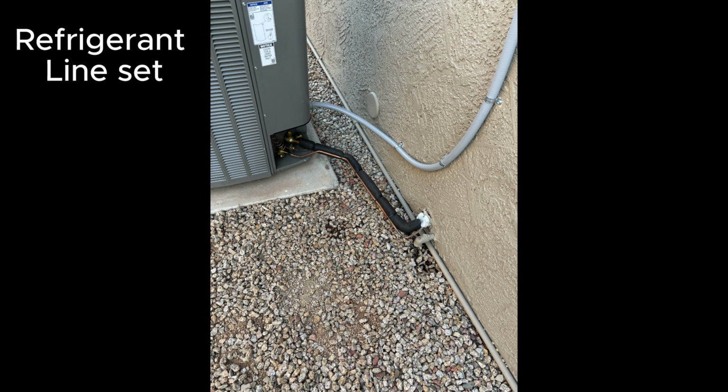So in the same way that airflow from the blower motor moves throughout the ductwork and it's a sealed system, there's copper pipes called line sets that connect your condenser to your air handler or furnace, and that is what refrigerant travels through between the outdoor unit, the condenser, and the indoor unit, which is the air handler or the furnace. So the refrigerant is like air, a medium that helps with heat transfer.